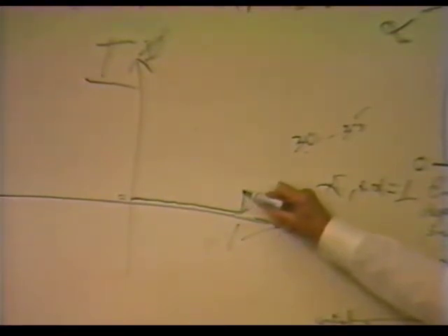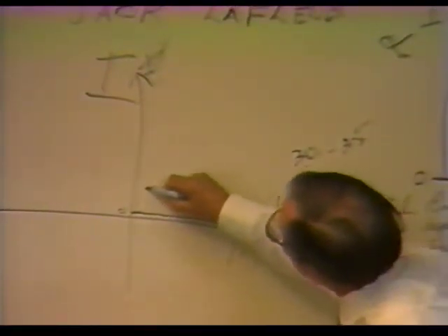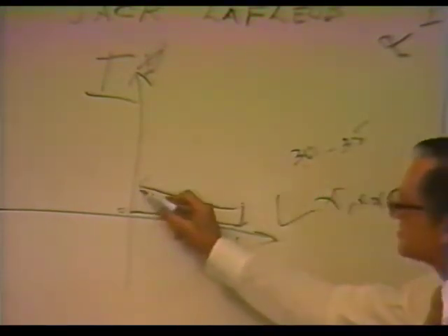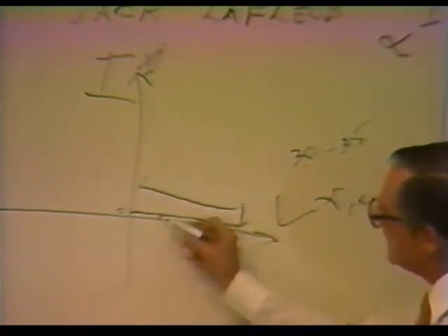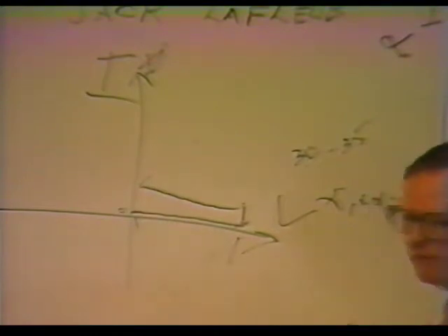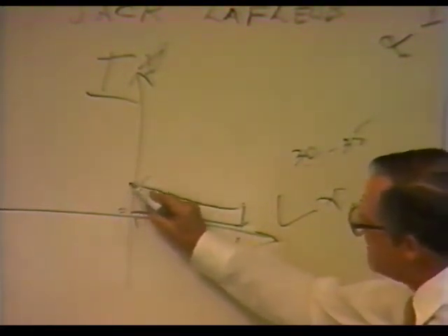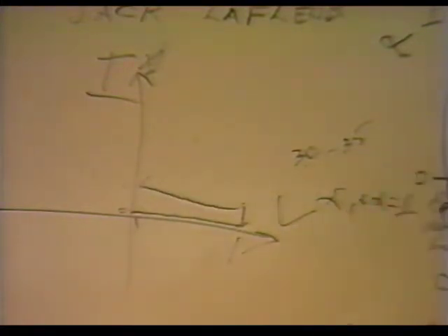The junction breaks down, and when it does, it swings back here in what we call the negative breakdown region, but it'll swing all the way back to a point where we have almost no voltage. It's a very low on state where we have almost no voltage, and that point right there is called the holding current. And what that is, the minimum current where the alphas will keep both those transistors in conduction.